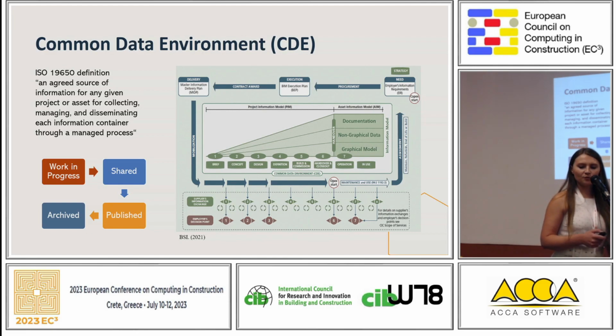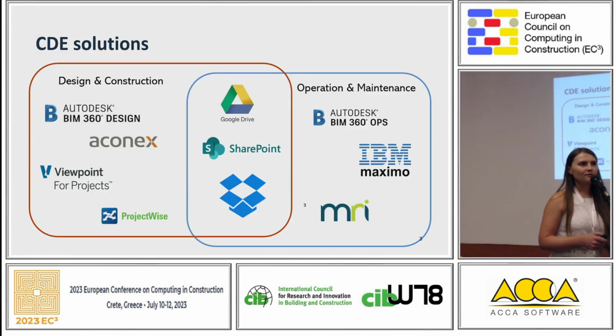And the CDE should be used basically for the whole life cycle, starting from the design through construction and operation and maintenance phase. So in practice, we have many different CDE solutions that we can use in construction. For example, in the design and construction phase, it is common to use BIM platforms such as BIM 360, but also document management systems like Aconex or Viewpoint for projects.